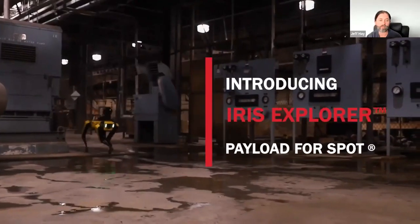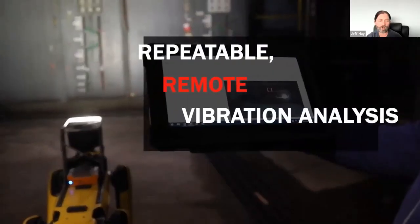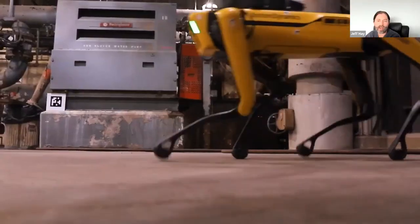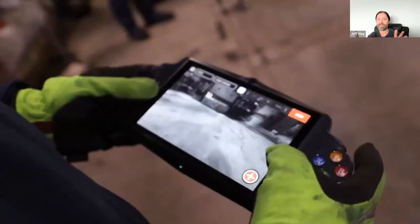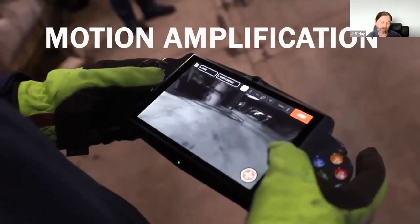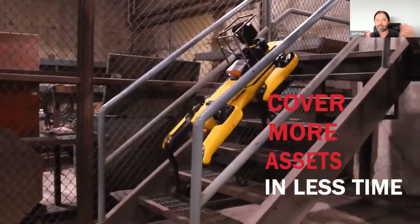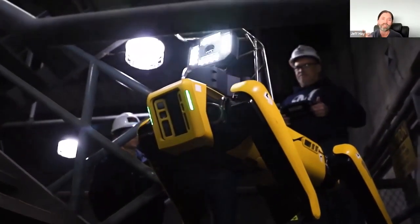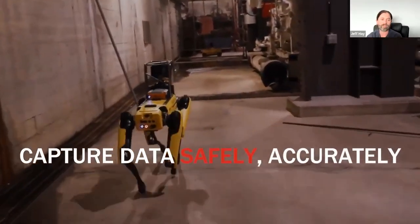But this is fully autonomous, and it's pretty amazing seeing it work. It will go through and automatically collect the data, and then automatically find the locations again if it walks to a new location, maybe a foot to the right or left. It will find the same locations that it measured previously and make the measurement, historize the data, store it, trend it, all that kind of stuff that you'd expect from route-based vibration collection.